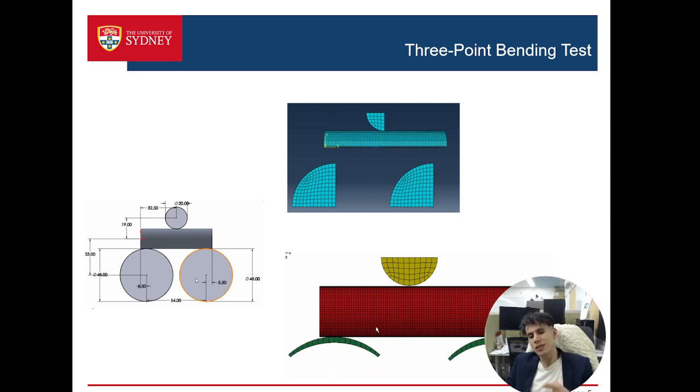I mean, in this kind of standard, in some cases, they just consider the shell, or they just consider the jelly rolls, which is inside of the shell. But in our experiment, we consider the whole battery. So the load is gradually increased until the specimen reaches its maximum bending capacity or failure points. And during the test, the applied load and resulting displacement or deformation are recorded.